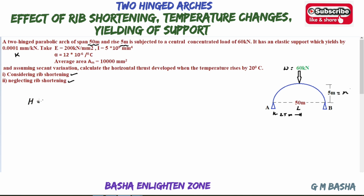The formula is H equal to integral of M dash y dx by EI, divided by integral of y square dx by EI. Whenever they ask regarding rib shortening, first take rib shortening and then neglect it.